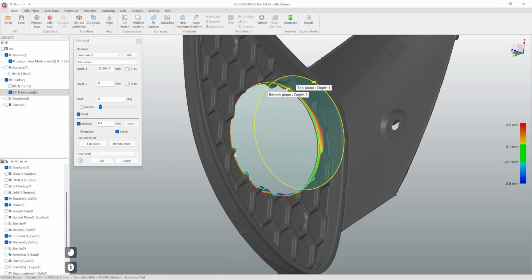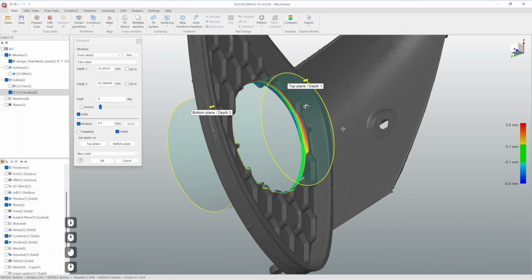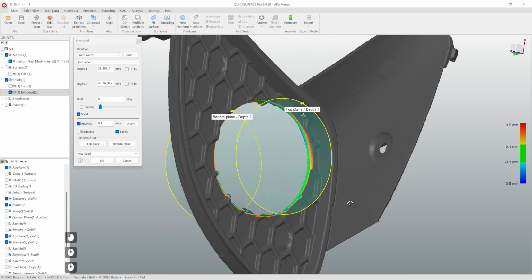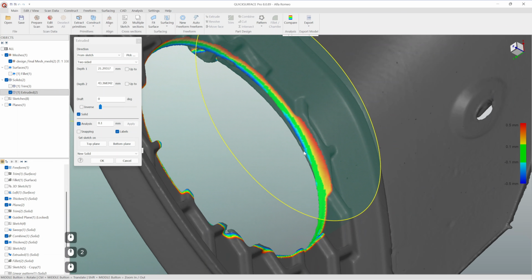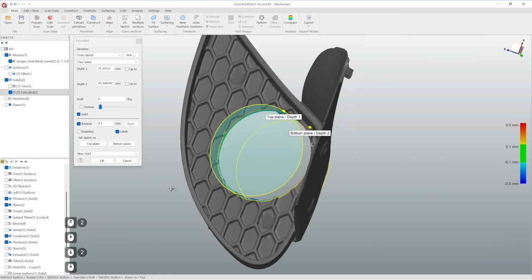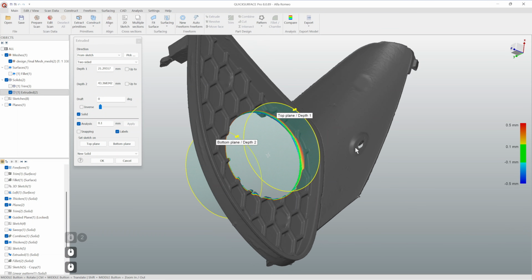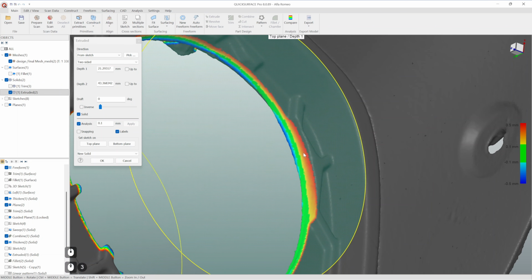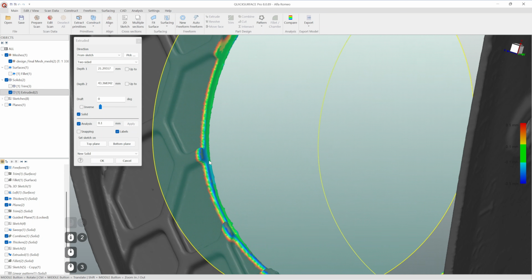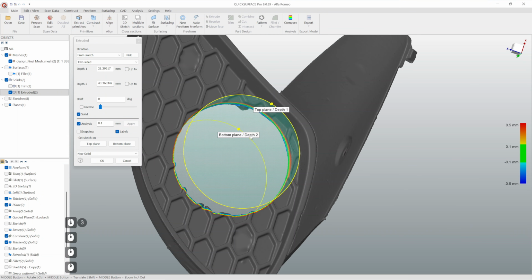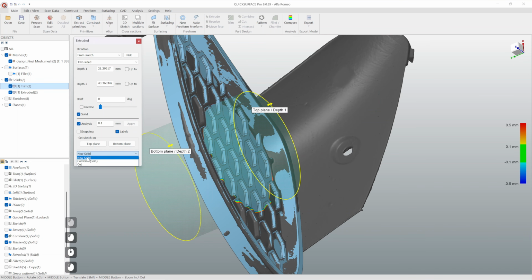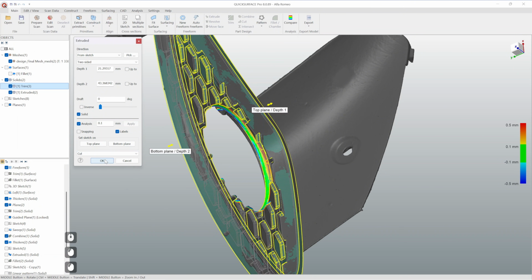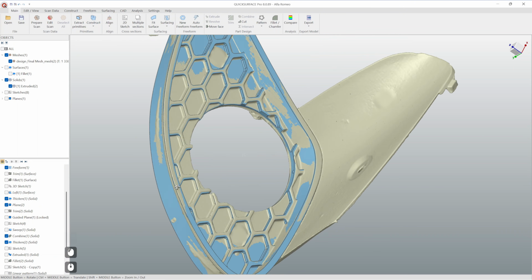So now hit extrude. Let's extend it in both directions. Here we can see the deviation analysis. Again, probably the extrusion direction should be slightly sideways, considering deviation tolerance on this side and this side. But for this purpose, I'm just going to leave it as it is. I'm going to unhide my solid and say I want to cut it with the extruded solid. Okay, like this.